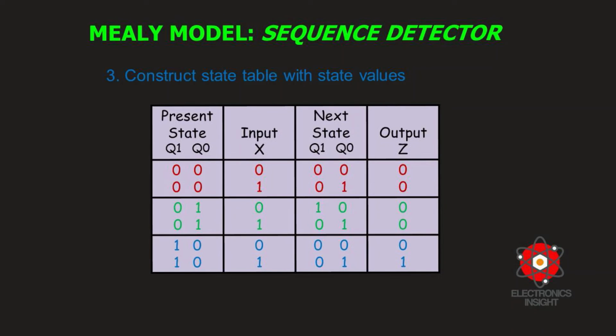Like if it is a 2-bit representation, 2 to the power 2, you will have 4 states. Since out of 4 states we are designing a finite state machine, we will fix only the finite number of states required. Here I require only 3 states, so it is A, B, and C. A is 00, B is 01, C is 10. This is for the Mealy model. Similarly, all your next state variables are also redefined with their state values.